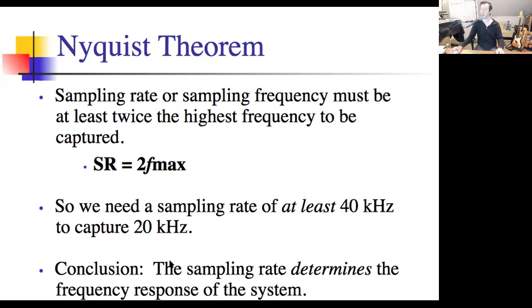So the sample rate of 10,000 hertz would give us a highest frequency of what? No, figure it out. I can't hear you. Did you figure it out? 10,000 hertz sample rate, the highest frequency would be 5,000 hertz, according to Nyquist theorem. Sample rate equals 2 times the highest frequency.